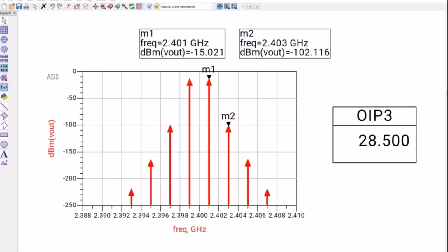What resistors do we use? Are they sort of RF? Every SMT resistor is an RF resistor. There is no special meaning. We are not using leaded resistors. They are all SMT. They are by default RF resistors. There is nothing special which is called an RF resistor.